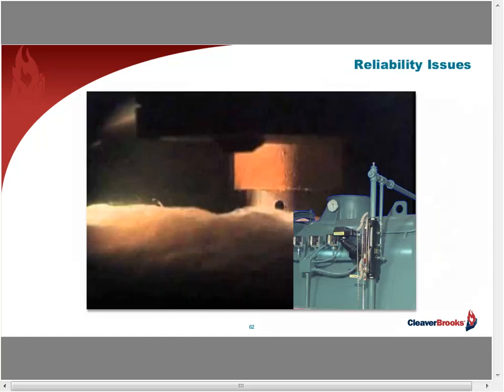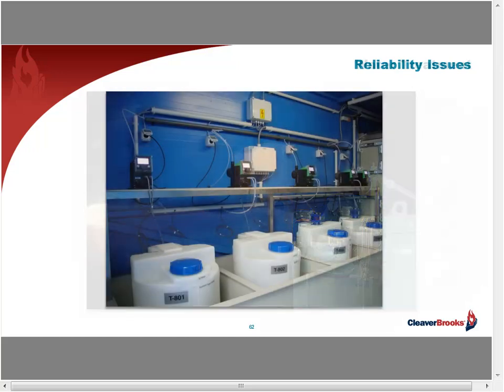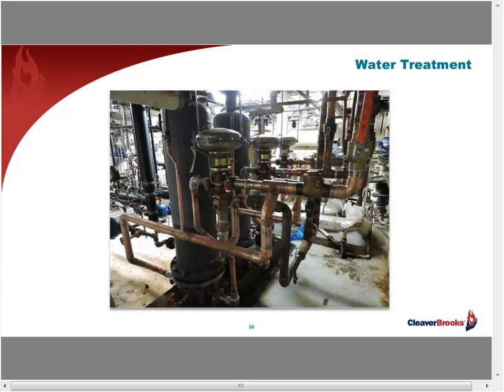I spoke earlier of another reliability impact area, and that's the low water cutoff. When it trips, caused by surging and dropping water lines in the boiler shell or the drum, oftentimes this can be traced back to a water treatment problem, which has gotten out of balance, requiring adjustment, or possibly contaminants coming back from the condensate return, and may be caused from a process malfunction, such as a leaking heat exchanger. You know, the cause needs to be determined quickly and a remedy applied.